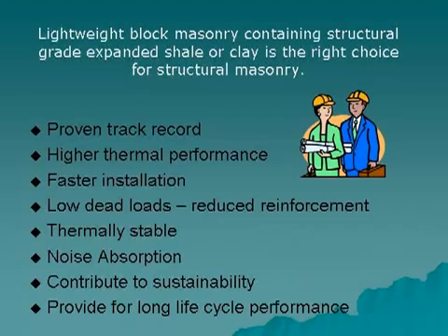Lightweight block masonry containing structural grade expanded shale or clay is the right choice for structural masonry. Consider its proven track record, its high thermal performance, fast installation, lower dead loads, reduced reinforcement, thermally stable, its noise absorption, its contribution to sustainability. It provides for long life cycle performance, and many other reasons too numerous to mention during this presentation.